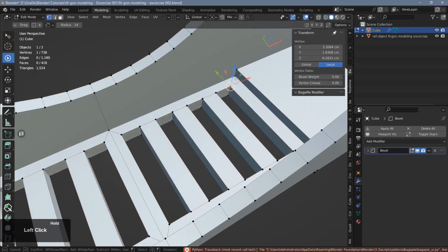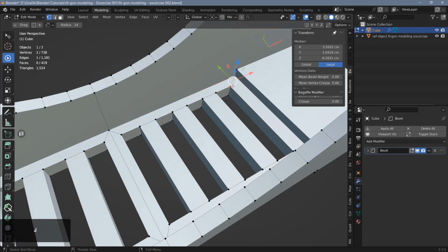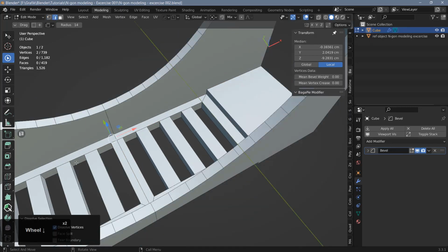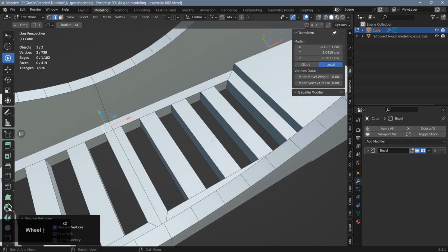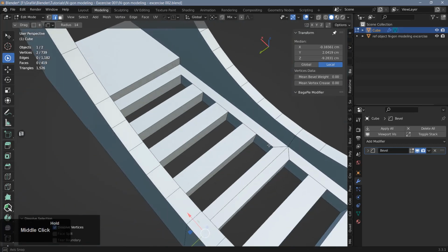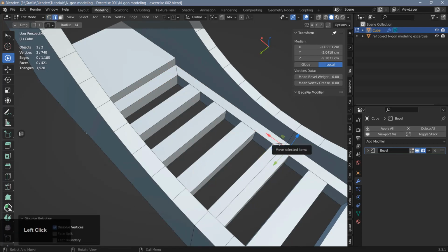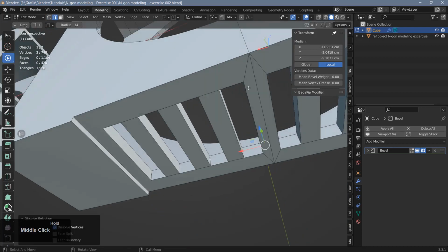We definitely need connections in the corners here, so I'll do this with the J key. And I'm also going to change the connection here at the center and dissolve these edges here. I'm not going to worry about the other side because we're going to mirror this over right to left. And we need to do the same thing over here. Let's create a connection here and here. And again, I'm going to dissolve these edges here. And then we also need to do the same thing at the bottom.